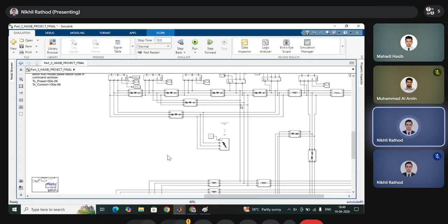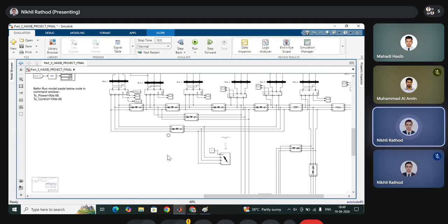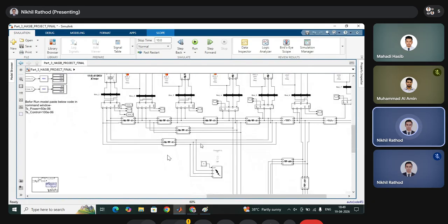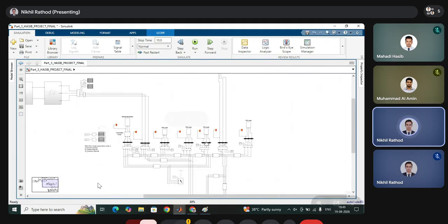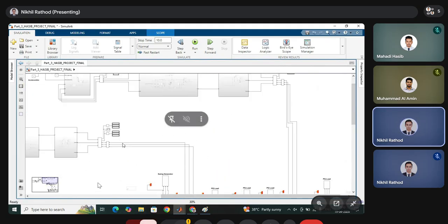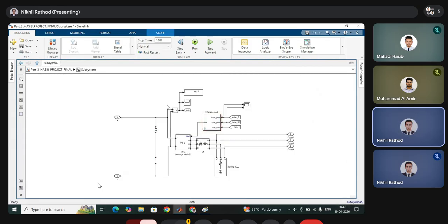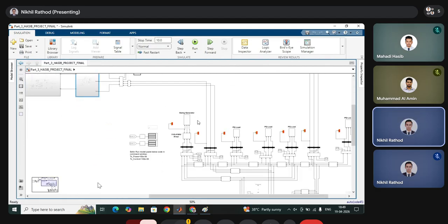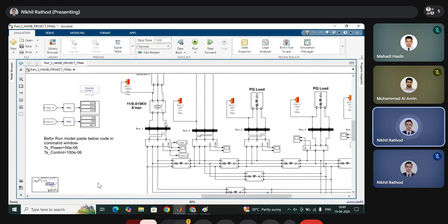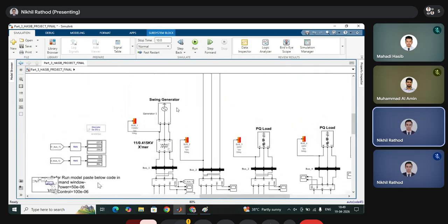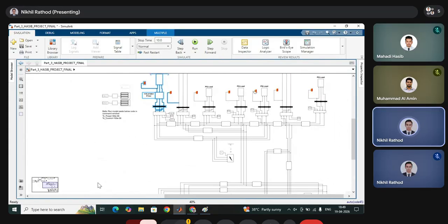So in this condition, we have created a fault over the transmission line. If the transmission line has a fault, you can see the influence coming. And the influence is more due to these converters, these VSC converters. And it takes more time to stabilize. But if the generator totally fails or if the grid totally fails, this generator must not fail. It's a swing generator, so all the load is coming over there.